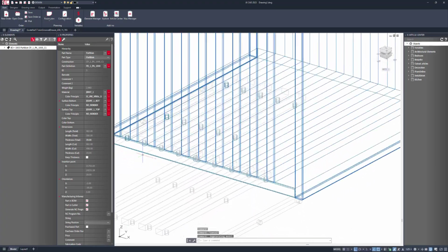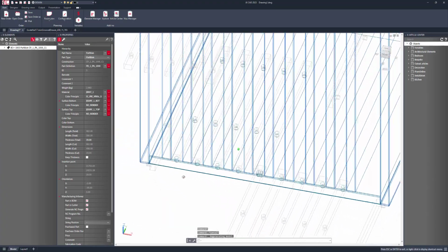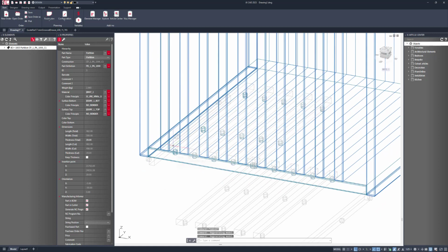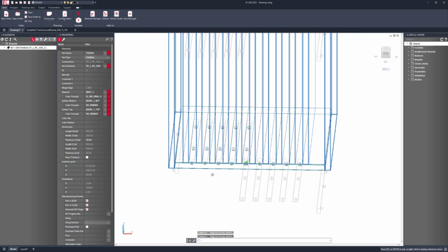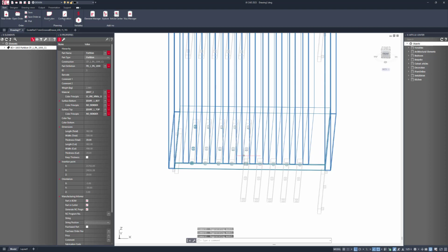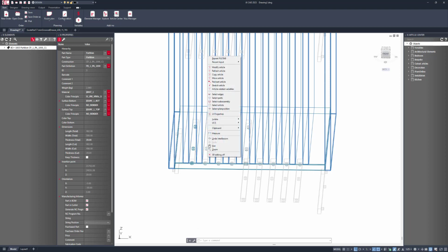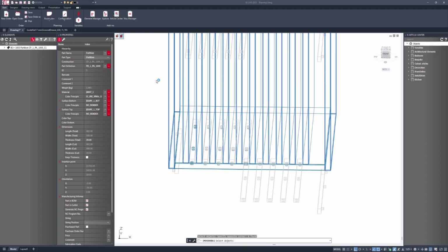Okay, now we've got a bit of an unexpected result in here, and that's okay, we can figure it out. Because the product is being flipped in here, we need to give it a handing, because it's looking at its position relative to the overall dimension of the product. So we want it to always know that it should be from the outside. It's probably easier to go to the organizer, and then once we're in organizer we can alter the settings within the connecting set.